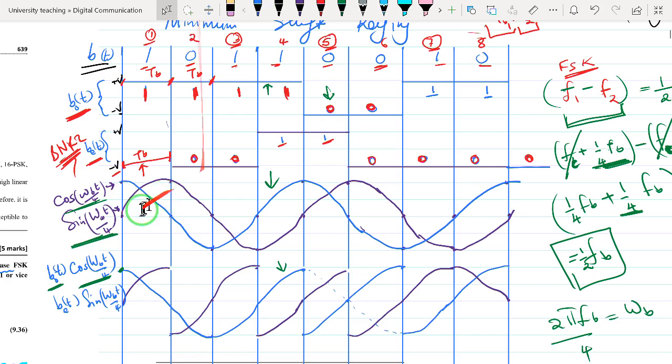So similarly, we are going to multiply the sine wave with the even bits. Remember, the even bits are the ones that we are representing here down. We start at the second Tb. So we are going to apply the same principle. When we multiply a sine with a -1 voltage, there will be a shift in phase. Assume it started at this point, and we have transitions to 0, it will change phase by 180 degrees for the 2 bit durations.